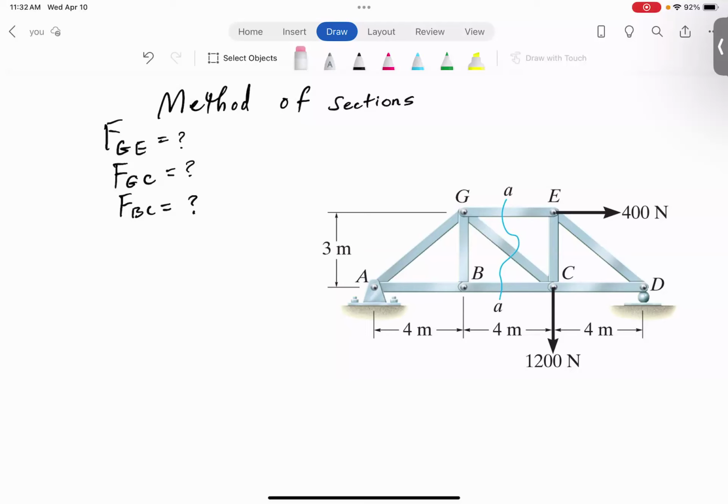So this is a simple, really, truss. Regardless of which side of a truss we pick, either the left side or the right side, we need to know what's going on at A and what's going on at the roller D. So we have a pin at A and a roller at D. You could select which side you want to pick, eventually the side that is more efficient to use. But first, we need to find the reactions at the pin, which is going to be AX and AY, and the roller reaction, which I'm going to call DY, right? Roller, just one reaction, pin, two reactions.